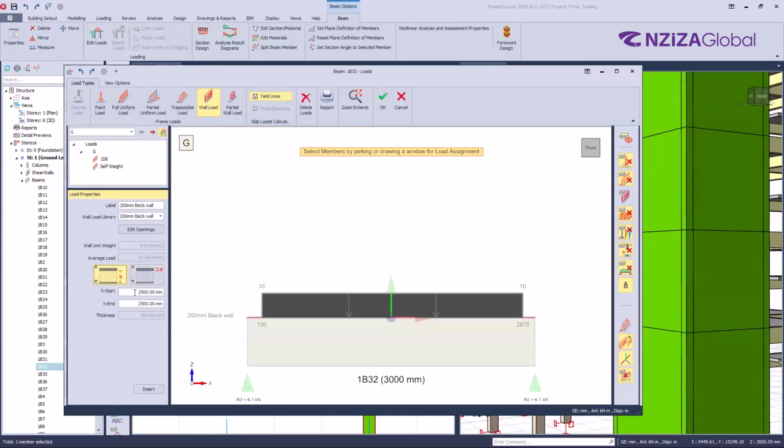If you choose the first one, here you will fill in the height of the wall, okay, the exact height of the wall, after deducting the height of the beam above the wall. If you choose the second one, you will put only the height of the beam, then the software will automatically calculate the exact height of the wall. So in my case, I have chosen the second one and I have put the height of the beam.